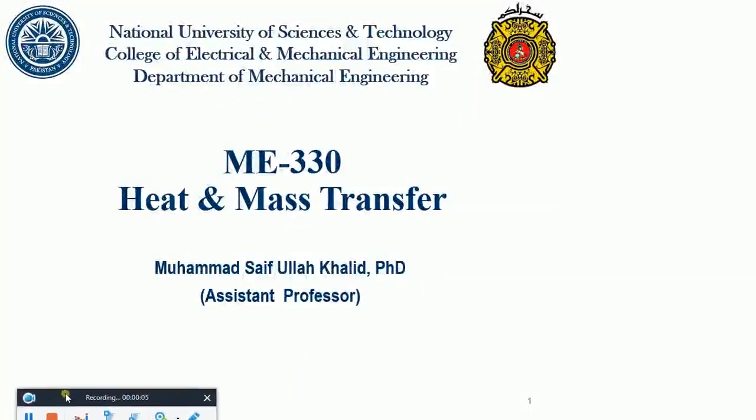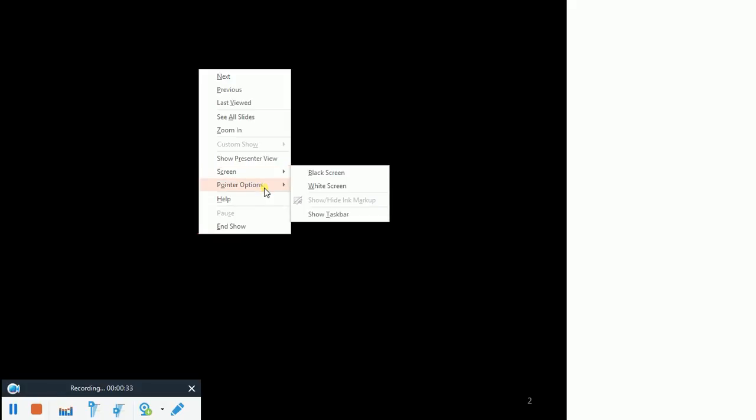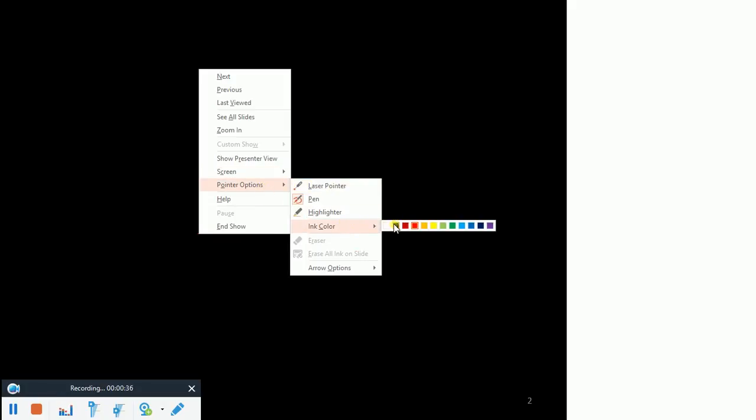So we are on the numerical techniques of unsteady problems. Yesterday we were at a point where we simply looked at forward difference in time and central difference in space. You remember that? What was the equation? We were talking about 1D unsteady heat transfer.